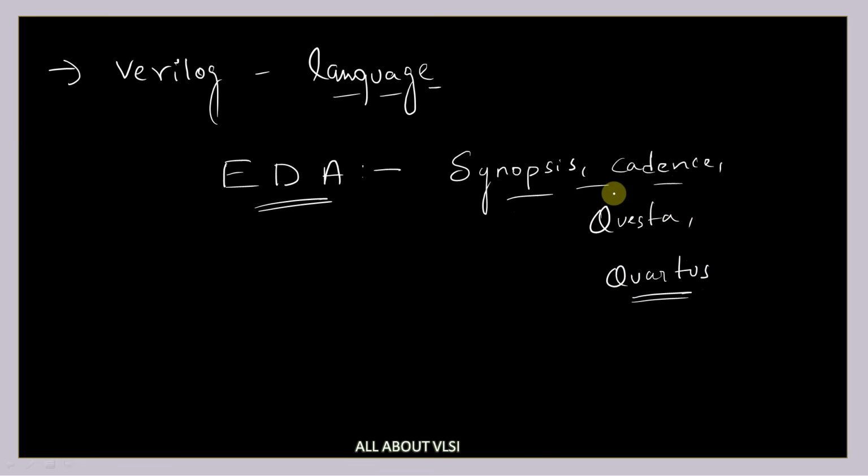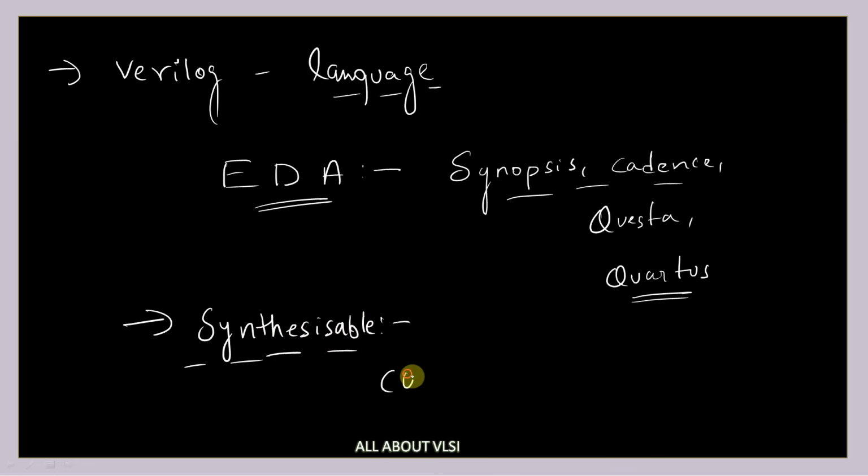So your main concern is to write your Verilog code such that it will be synthesized. Often people get confused, and often people lag in this particular concept, which is synthesizability. Verilog is a synthesizable language. What do you mean by synthesizable? In the sense that your actual code will be converted into a gate level netlist or hardware.